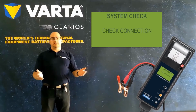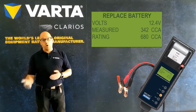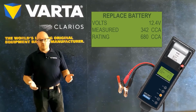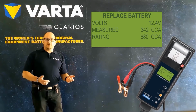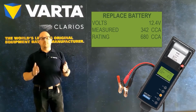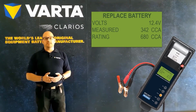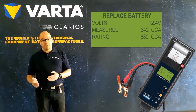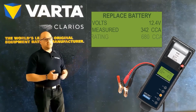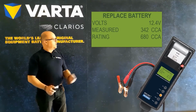When the test is complete, even though the tester will likely give you an accurate response, it is helpful to understand why it is given that response. The voltage reading shows battery charge available. A little understood but very important factor is the CCA rating. This shows how much power the battery has to crank the engine. If this is lower than the rating of the battery, it indicates there could be a problem with the power of the battery. This battery is rated at 680 CCA, but the measured value is much lower at 342.